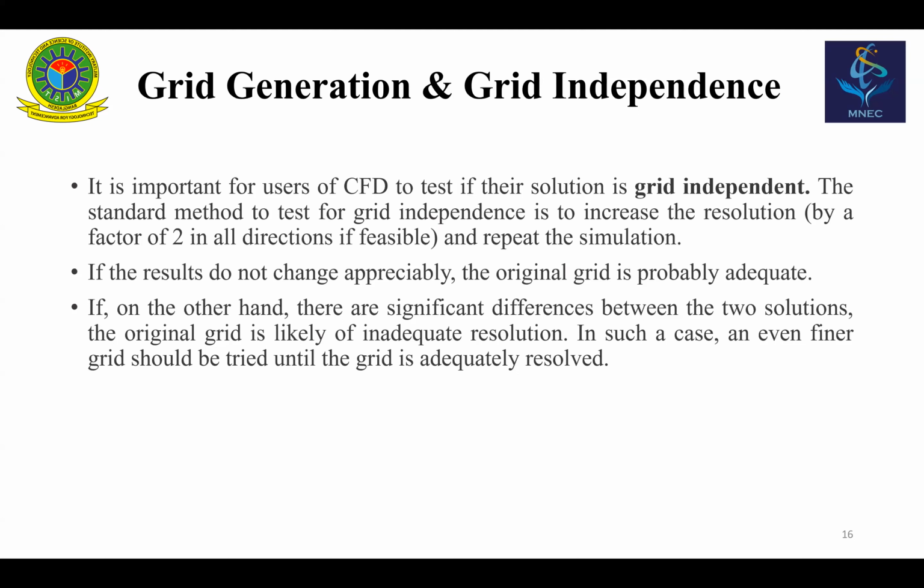All of you have used AutoCAD or SolidWorks. This has got the same interface. You have to create the geometry, and after creating the geometry, then you have to create the mesh. And while creating the mesh, we have said that you have to consider the quality of the mesh, and also you have to have a close look at the number of the mesh or grid that you have to produce. Then you have to perform the grid independence test. So this is so far the procedure.